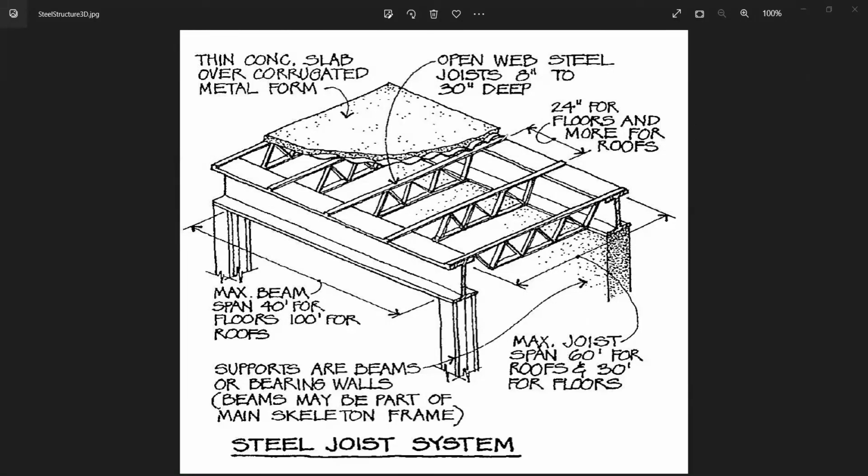Okay, so as I mentioned, we'll be using these joists, and they are going to be resting on some of these wide flange members. The ones that will receive the joists will be the deeper one. So remember that first number, the W16, is deeper than the W14. So we'll use the W16s where the joists are bearing on them, and then we'll run the W14s along the same line when they're parallel to those joists.